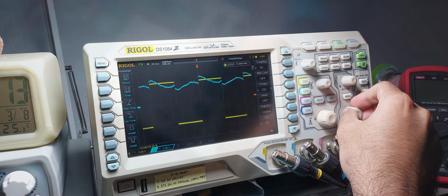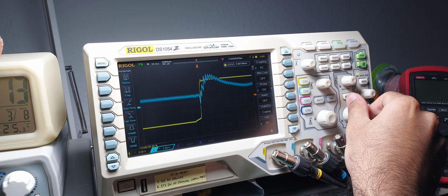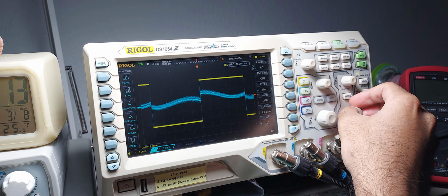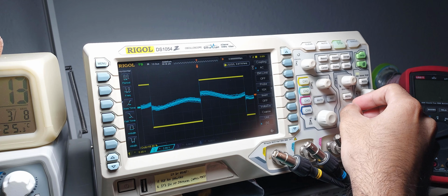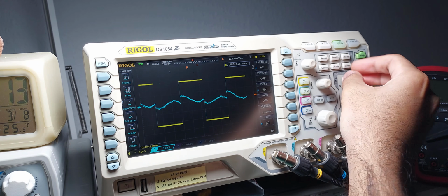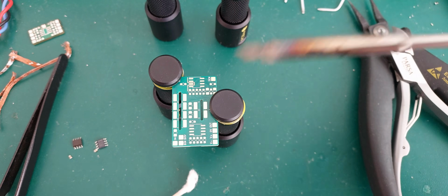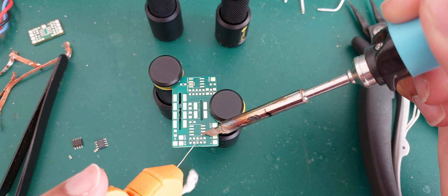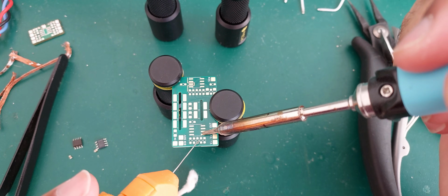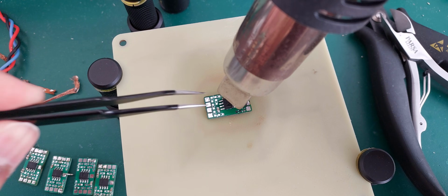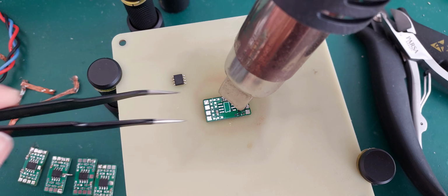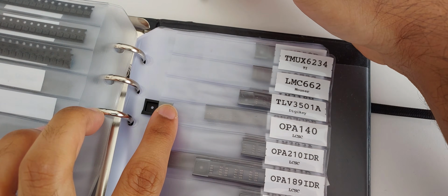Back on the filter side, I was not having much luck with the ripple of my discrete filter, which is just barely under a millivolt peak to peak. Once again, bigger capacitors are not always better. Since I had some tried and tested LPFA V1 boards anyway, I decided to populate them and see if using them improved performance. Thanks to my increasingly constrained budget, some parts had to be salvaged from older projects, but others are taken from fresh stock.